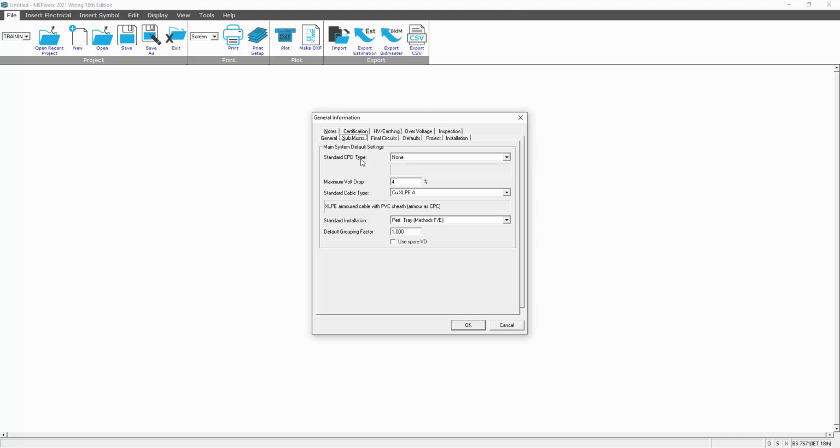I'm just building this job up on the fly for the training course, so at the moment I'm just going to use BS88s because they're fairly flexible. So when you do your project, in reality, you might know that you've got 70, 80, 100 amp boards, 35 amp boards, whatever, and you might decide to use, I don't know, NS100s or C60s or whatever to protect those circuits. So you will have a better judgment on setting up these devices early on.